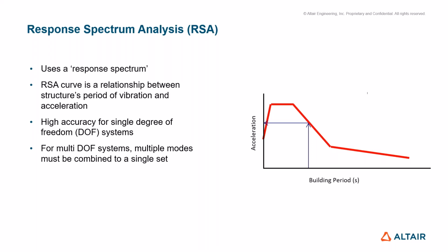So the methods used for this will actually prevent the RSA method from being used for things like nonlinear elements where you might have tension or compression, because the combination methods for these different modes are going to lead to a loss of, for example, negative and positive signs when calculating nodal displacements or axial loads.